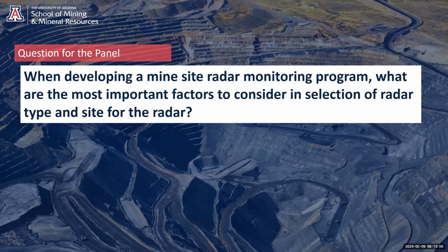From the geotechnical or rock mechanics point of view, consider what the expected mechanisms of failure are: fast, rapid, brittle failures, or long-term deformation? Is it circular rotational failures, or structural? If it is a structural type of failure, then where are you going to position your radar so that it can pick up the movement in the preferred direction, driven by the structures behind the unstable wedges? The money, of course, maintenance, communications. But